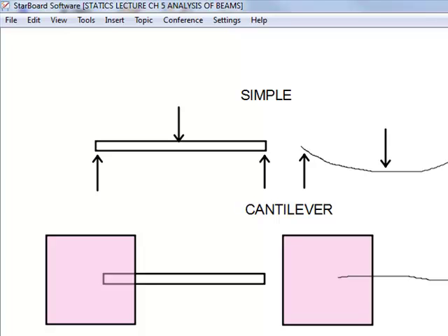And remember that a beam is a structural member resting on supports at its ends. So, that's pretty simple. There's beams holding up this floor that are resting on columns, usually. Beams tend to bend rather than lengthen. A column will lengthen or shorten. It'll be in tension or compression. And a beam will tend to bend. Of course, there is some tension and compression in that bending, but overall, we just say that it bends. It doesn't shorten or lengthen.